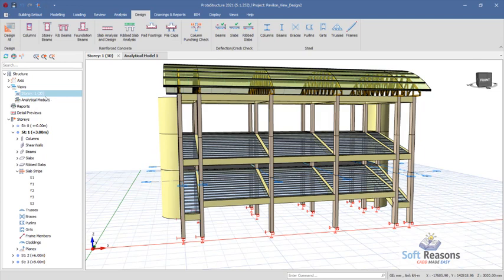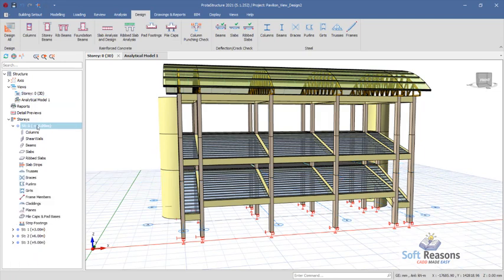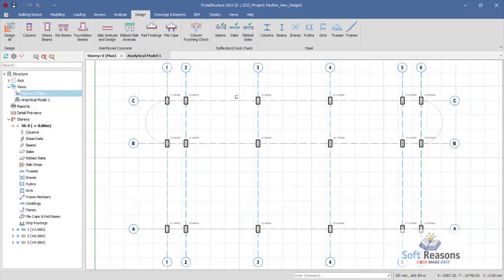So we can navigate to the plan view of the foundations, double click on story 0 right there, and then enable the plan view. This area is going to be taken by the raft on beam. We can also support the raft on beam with pads, if necessary, but this is for the sake of the lesson, making you understand how to make use of most of these foundation options.